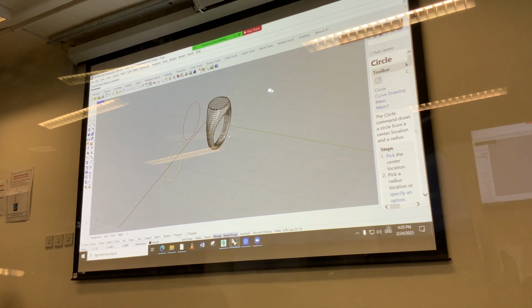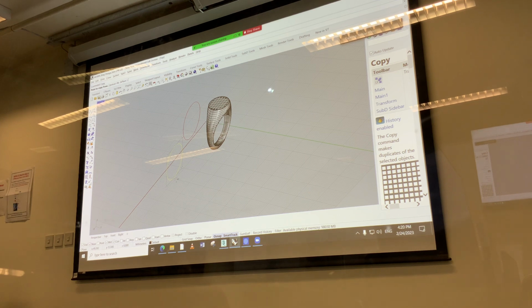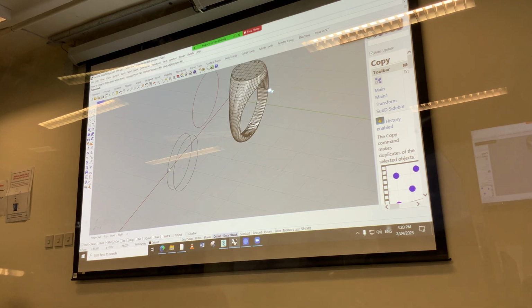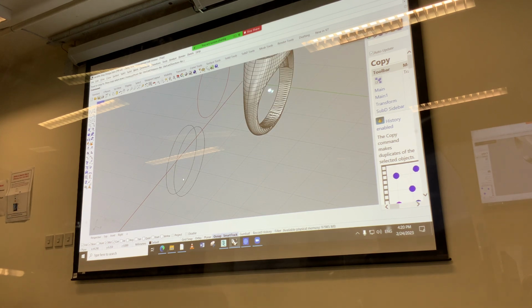So well, the next size is obviously to make sure how thick your ring is, and within the 3D printing elements of SLS and SLA, we can clearly say to copy this ring by about 3 millimeter should do the trick. So if we hold the shift bar, type 3, and then we hold the shift button to make it orthogonal. Then we have the main constraints of our ring, which is the size that it fits in, as well as the thickness of the band.